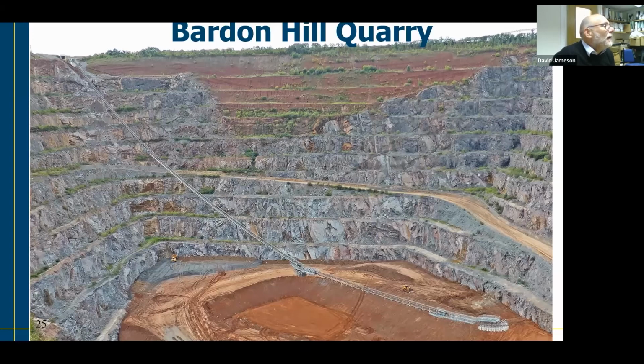But up on the corner there, you can see where the initial pivot tower is. We needed to cut a slot into the upper benches in order to accommodate the rope conveyor. And in cutting that slot, that would produce a lot of rockfall or potential rockfall, which could then fall over the face and be incident on the main haul ramp, which is spiraling down the quarry.